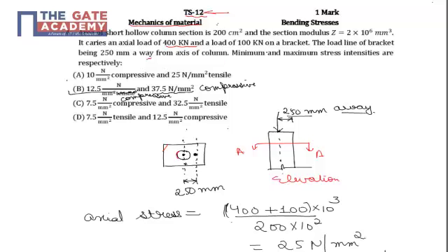So here we are having two loads that are acting perpendicular to the face of the column, or parallel to the axis, which is shown by this red line. Both these loads will be producing axial stresses, but here this end will be subjected to compression and this will be subjected to tension due to bending. So this face, let us say this is A, B, C, D.